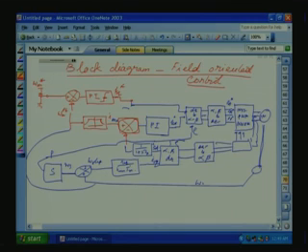But if you see, the slip is depending on TR, that is the rotor time constant. So rotor resistance can vary with the temperature. So wide variation is possible here. Many control schemes are available for parameter adaptation, that is, how to adapt the rotor time constant with respect to temperature. Many papers are available in the literature, but we will not be dealing with that now.